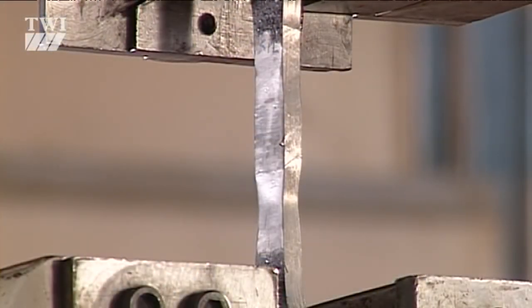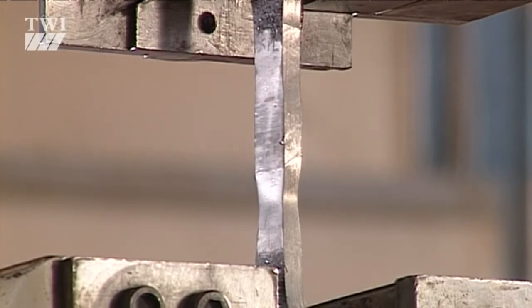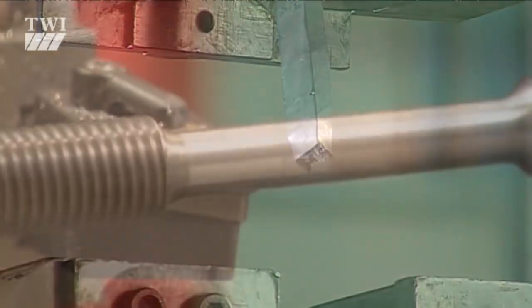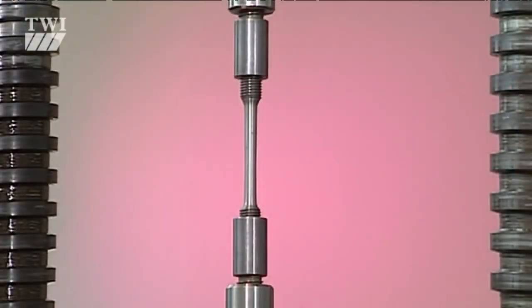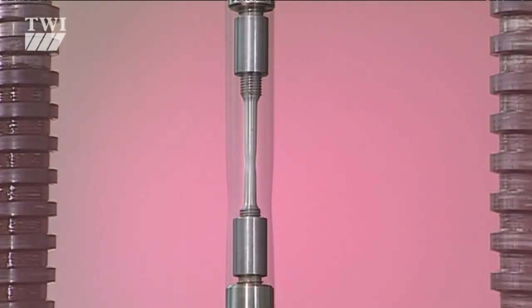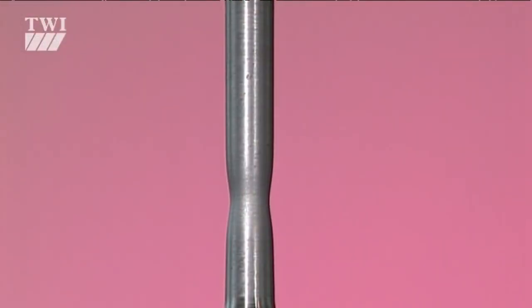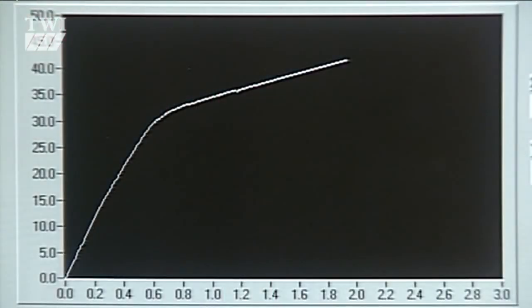Tensile testing, both a qualitative and quantitative test. In a nutshell, a suitably prepared specimen like this, machined to dimensions dictated by the codes, is pulled apart uniaxially at a specified rate. Both the load and the test piece extension are continuously measured and recorded.